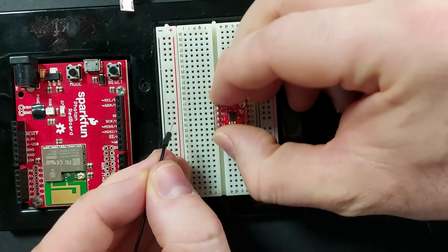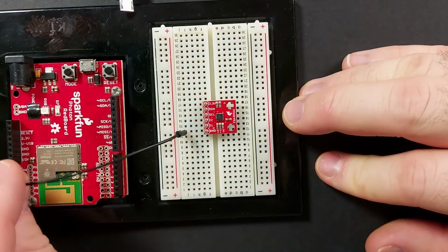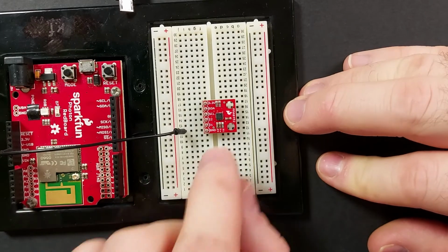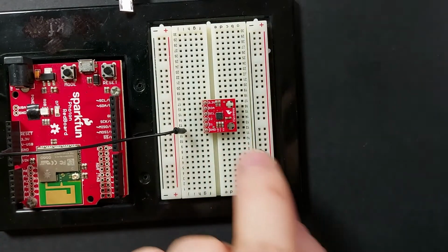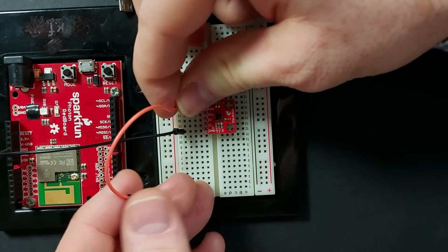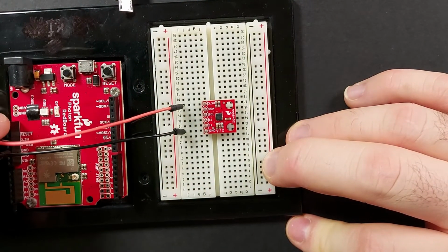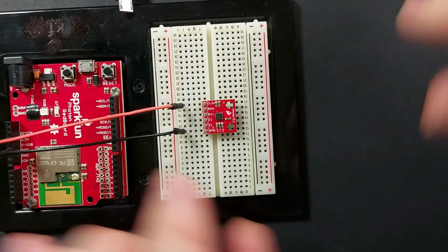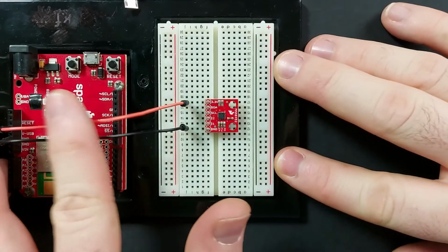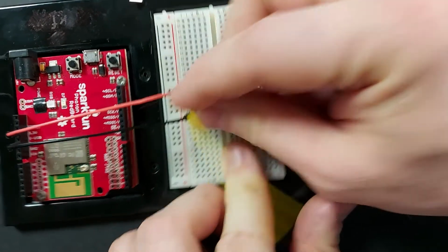The connection is very simple. You just follow the instructions on the board. So I'll just move the breakout here, the sensor here, connect the bottom one to the ground because it says GND, and the voltage one is 3.3. Also be careful not to put it in VUSB because that's going to be too much, because VUSB is 5.